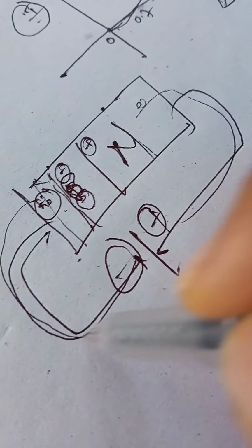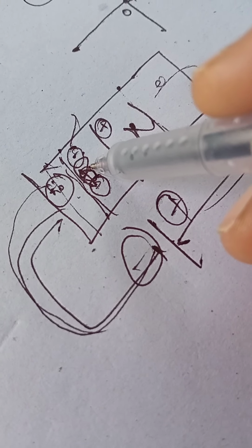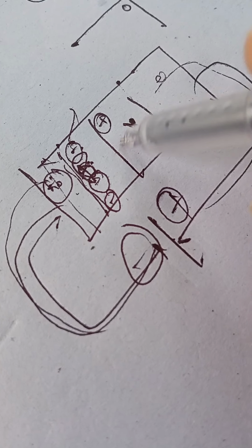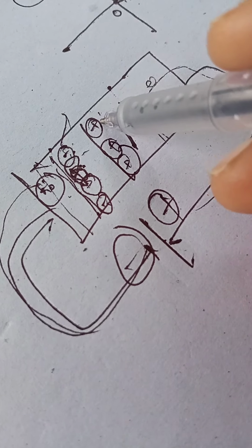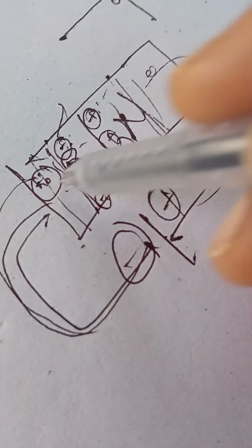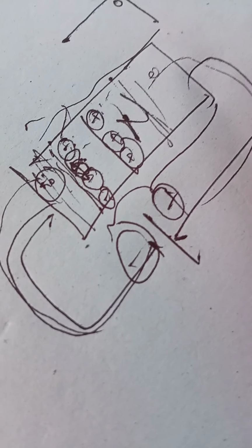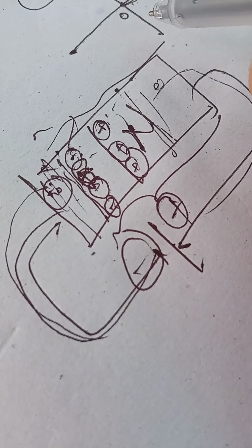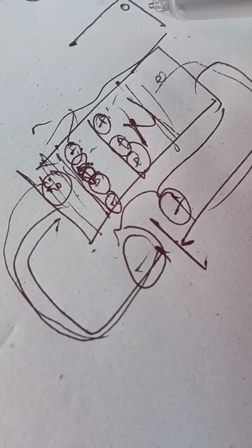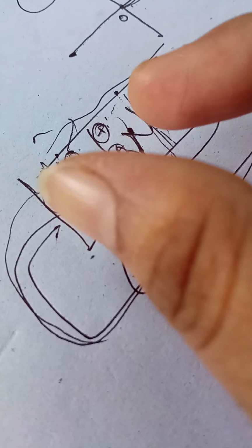Because all the majority carriers get attracted towards the battery. Then the leftover is only the ions which are present here. The concentration of the negative ions near the junction, and similarly the concentration of the positive ions at the junction, increases. As a result the depletion region becomes wider. So that means the built-in potential width is going to increase. Once it increases, the strength of these ions is more, and it stops